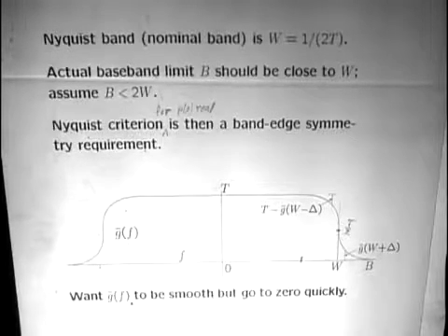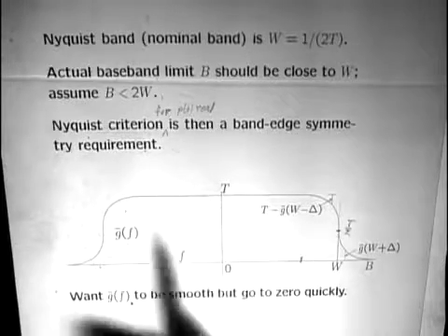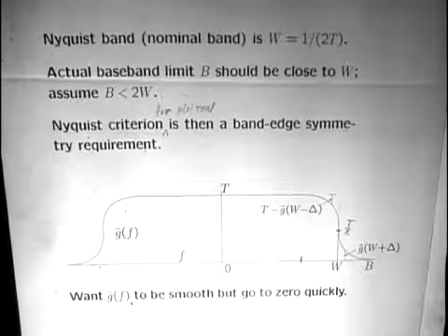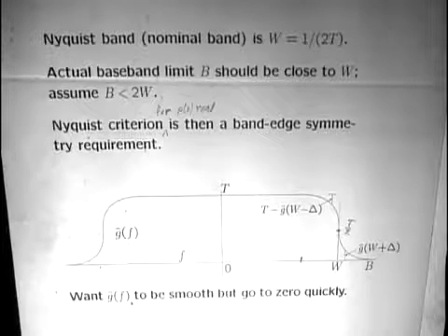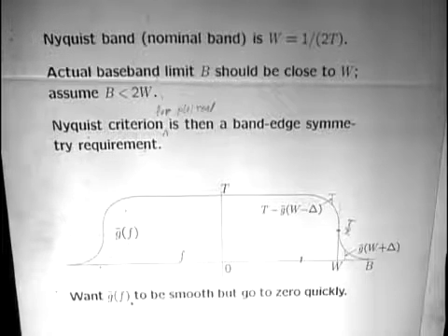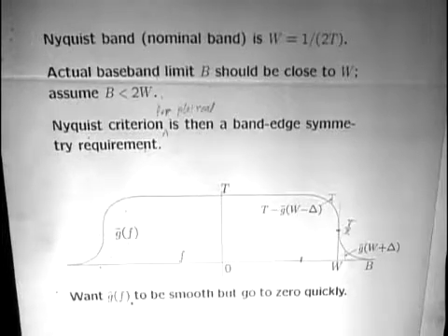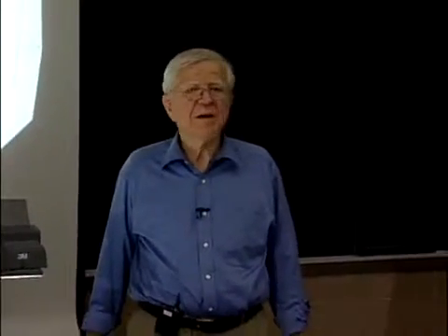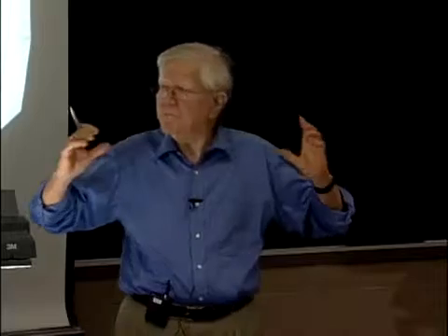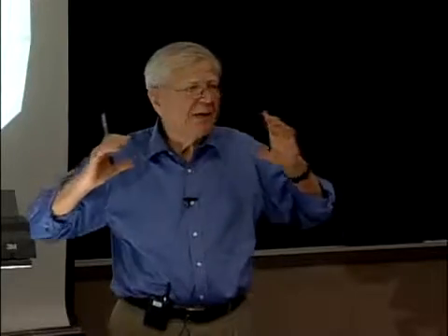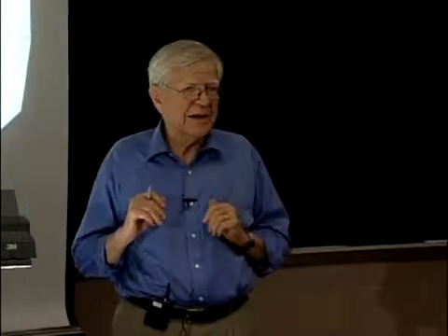The sinc pulse, because there's a discontinuity in the Fourier transform, can't go to 0 any faster than 1 over T. And something that goes to 0 as 1 over T goes to 0 very, very slowly. In other words, you have enormous problems over time, and you have enormous delay. And since you have so many pulses adding up together, everything has to be done extraordinarily carefully.